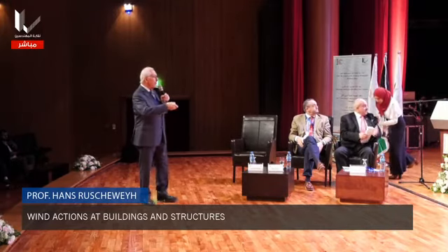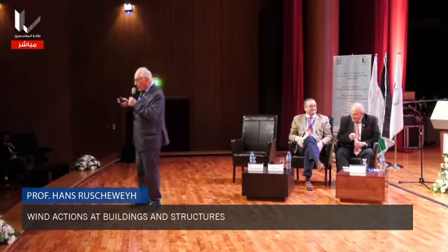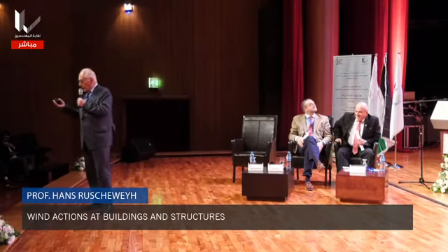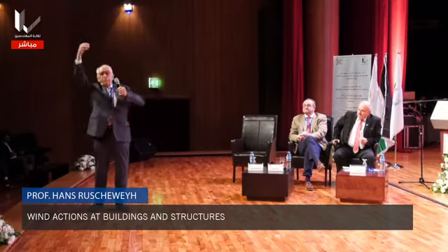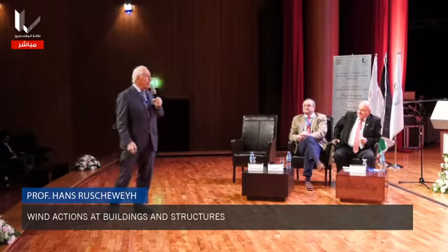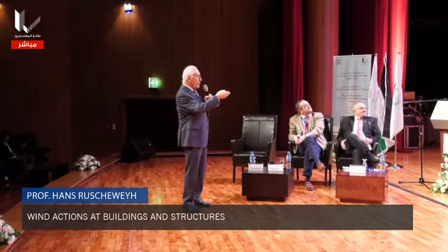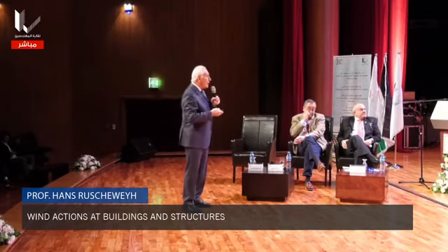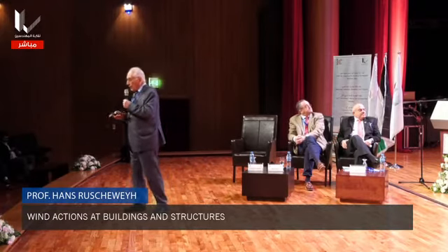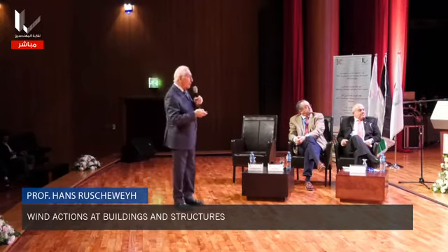The next point I will speak about is wind comfort. It is well known, when you approach a large building or a big complex and the wind is blowing, there are special places or points where the wind is increased. You turn around the corner, suddenly you have a wind on your body. This is wind comfort. Here, three examples. You see here the wind situations where the wind may be large. And then this can be handled in a wind tunnel. You can find out the area where the wind is high, and then you can calculate the comfort with comfort criteria.